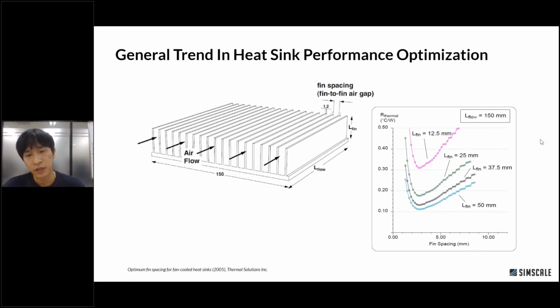So this simulation result is suggesting that the effect of increased thermal resistance of the heatsink when we place the heat pipe a little bit lower is bigger than the advantage of reduction in air path blockage by the heat pipe. So this simulation result is really giving us the insight that it's better to just position the heat pipe at the center of this heatsink.